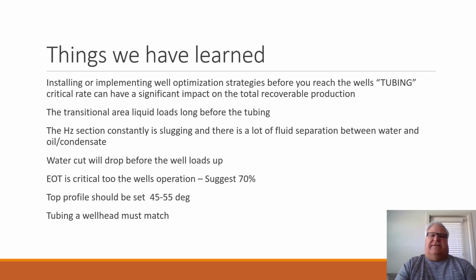We can prove, if you go to any one of your wells that produces any kind of water and you go to start it up or you need to swab it to bring it on, I almost guarantee you those first few swabs are going to be nearly 100% water, even if you're at low rates, 10% or 8% of water cut. You're going to see mostly water that comes back, and then you'll go back to your normal cut afterwards. That's a buildup and a separation that's happening in that transition area throughout that wellbore. So you can get some very dynamic actions, fluid separation, constant slugging.